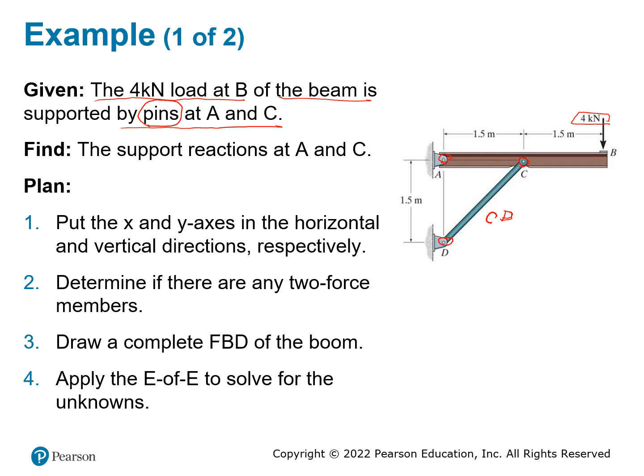A to B is not a 2-force member because you have a force at A, you have a force at B, but you also have a force at C. So this is not a 2-force member. This is a 3-force member, which is going to be different from a 2-force member. If this is a 2-force member, that means the force here is going to be equal to the force here and is going to be along this line. So I can simply assume the reaction force here is going to go along this direction.